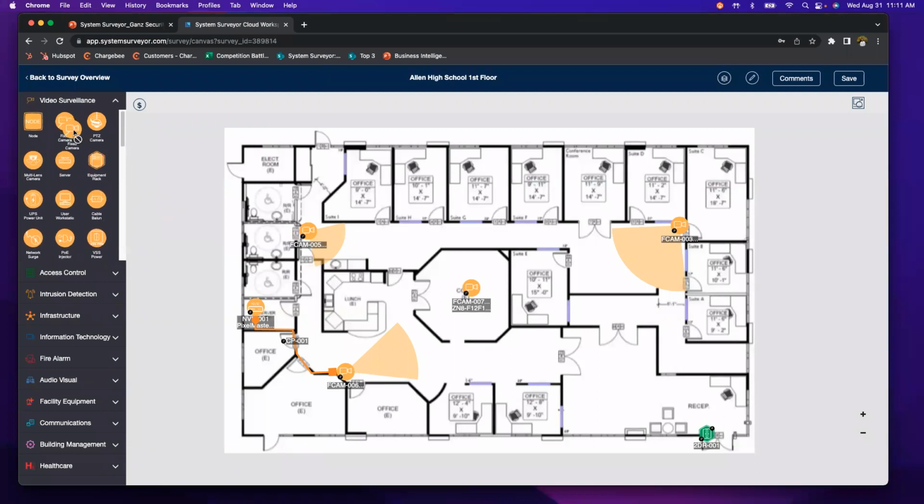Simplicity in and of itself: if you have a card reader that's reliably plugged into either a small-scale access control system or just an alarm panel, and we use one of our recorders like the DigiMaster or the PixelMaster, which both can do IP, and we have an IP camera in the fisheye, you can tie through relays from the alarm panel into that recorder for additional notifications and additional recording functionality. That gives you the simplest setup, because it's just the camera plugging directly into the recorder and a wire going from the relay on that recorder to your alarm panel.